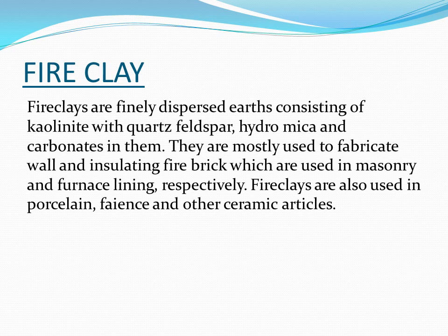Last that we are going to study is fire clay. Fire clays are finely dispersed earths consisting of kaolinite with quartz, feldspar, hydromica, and carbonates. They are mostly used to fabricate wall and insulating fire bricks, which are used in masonry and furnace lining, respectively. That is both in masonry and furnace lining. Fire clays are also used in porcelain, faience, and other ceramic articles.